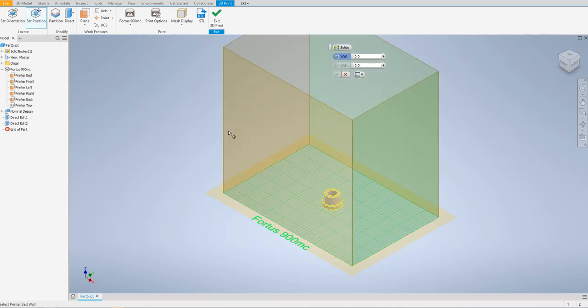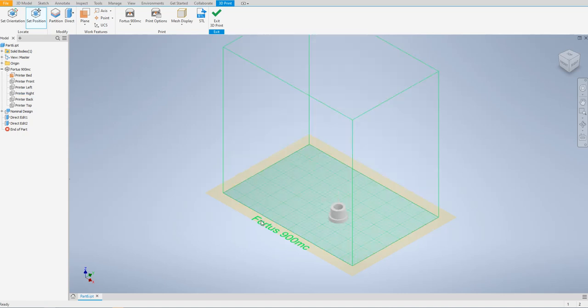You can select, as example, I want the position from this wall. As you see, it's now 0. We can say 200 as example. You can go to wall number 2, this wall. You can set this distance, now it is 0, say 300 as example, and then press OK. If you also want to change the orientation again, you can set the orientation like this.